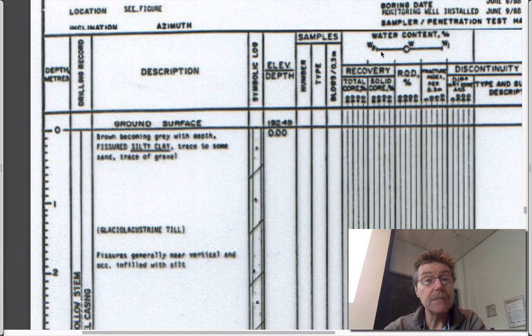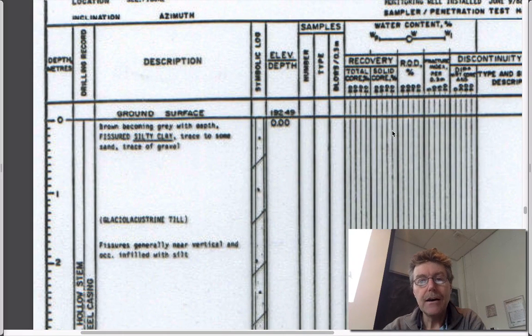In the samples that are taken back to the lab, what is the water content? What is the plastic limit? The amount of water you have to add to it before it becomes plastic. The test is you can roll it into a sausage that's 1/4 of an inch in diameter or something. The liquid limit is where you can add enough water. So I guess this is when you can dry it enough to roll it into a sausage. What is that water content? This is what is the water content you have to add until it flows like a liquid. And so these are both index tests for soils. And so these would be the measurements if it was a soil.